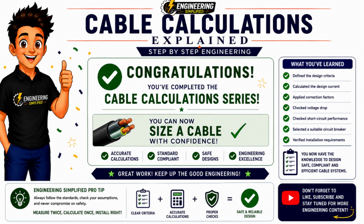Congratulations! You've successfully completed the complete cable sizing process from start to finish. Together, we've defined the design criteria, calculated the design current, applied correction factors, selected the correct cable, verified the voltage drop, checked the cable against short circuit conditions, and finally, selected the correct protective device. This is the same logical process used by electrical engineers every day when designing safe and compliant electrical installations.